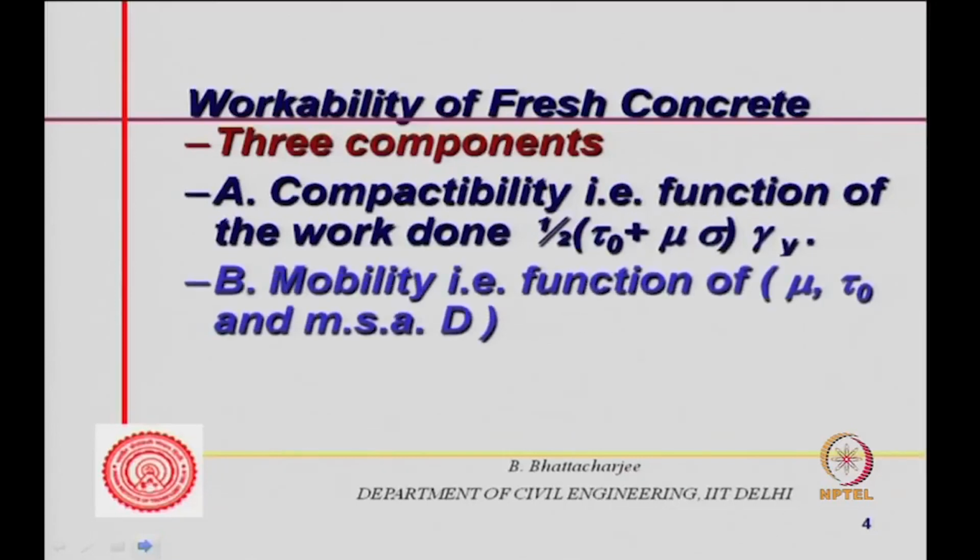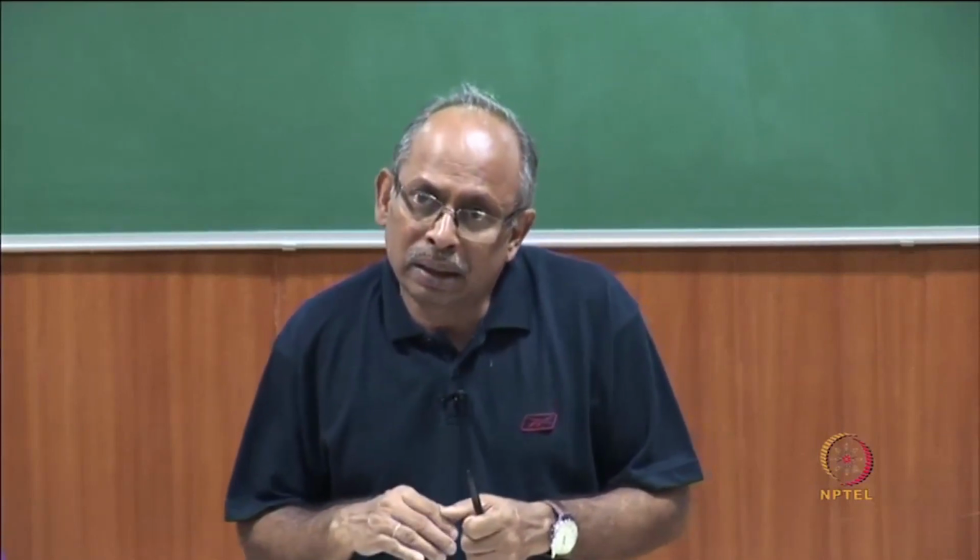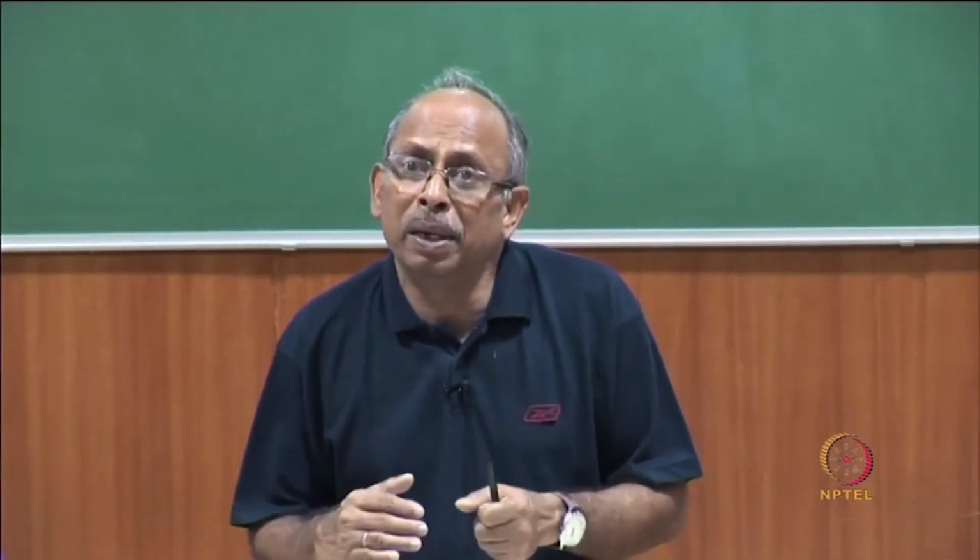So, this is how easily you can compact. There is the energy required to actually cause some movement, some shear stresses, shear strain, and that results in compaction. Mobility is the flow. So, I should be able to drive out the air, and that is compactability, and if I want to drive out the air, there should be shear, and it should show a Bingham kind of behavior.